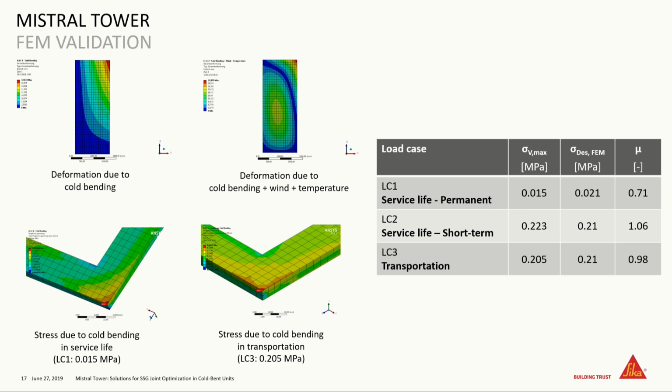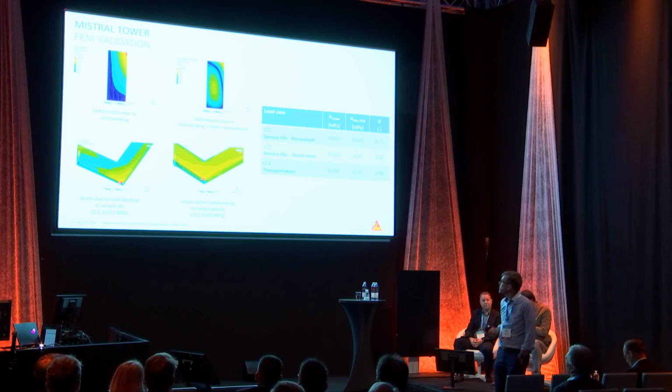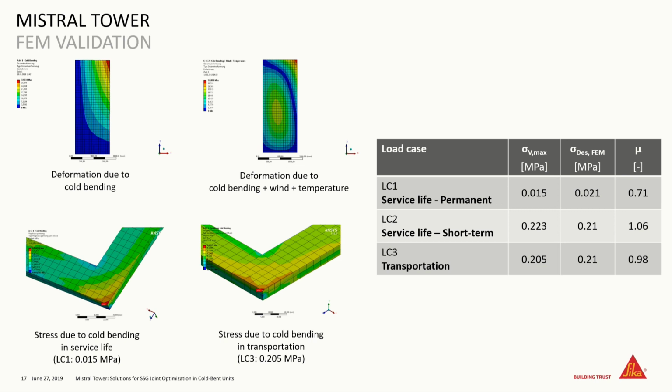And secondly, of course, for revalidation of the values, comparing with the design stress, the standard specimens we are using for this, called H specimen, are not the best ones in this regard. So using values out of pure material data is much better. But finally, the finite element method calculation just reconfirmed that the calculation done before in a manual way was right, was okay, and then the project was realized afterwards.